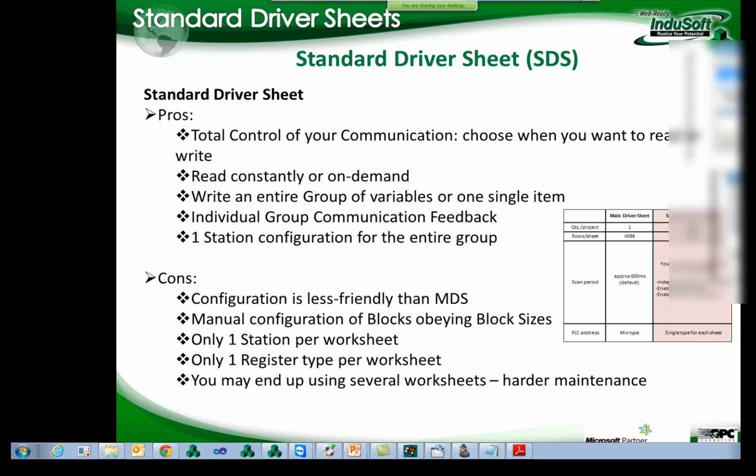I got a question here: is CodeSys compatible with version 6.1 of InduSoft Web Studio? Yes. When you download the driver from our website, you're going to install it on 6.1. That's going to install also the other communication libraries that we need for that driver. But most importantly, you need to have the latest CodeSys PLC handler.